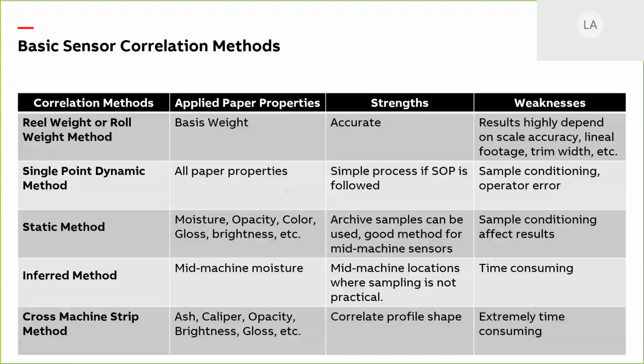How about single point? Just before you turn up a reel, the scanner head package is put in a single point position, and a calibrate sample is performed at the scanner. At that time, it will collect the average measurements during the calibrate sample time, and then report the results as a sensor measurement.